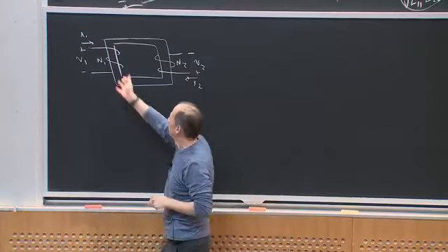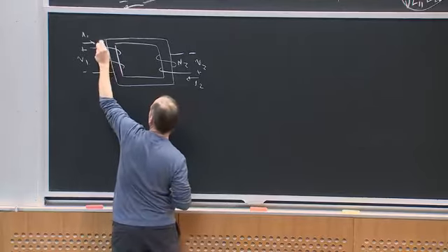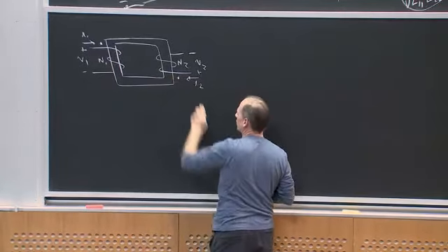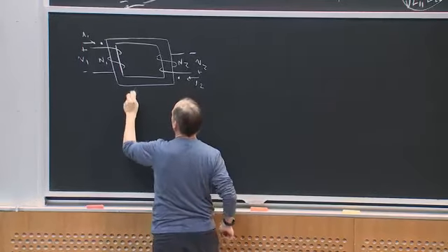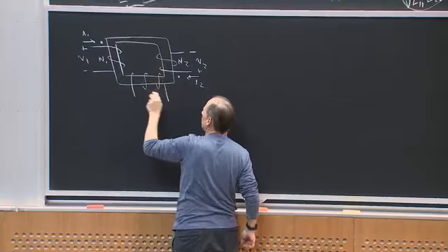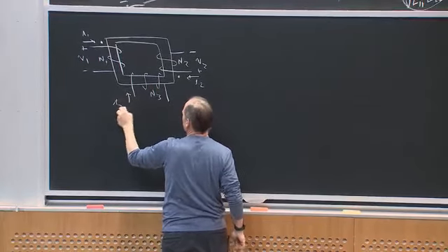and notice that positive voltage here throws flux around the core this way, so I have a dot here. Likewise, by the right-hand rule, I have a dot over here. Let me add one more. I'll have N3 turns on this one. I'll have I3 and V3.